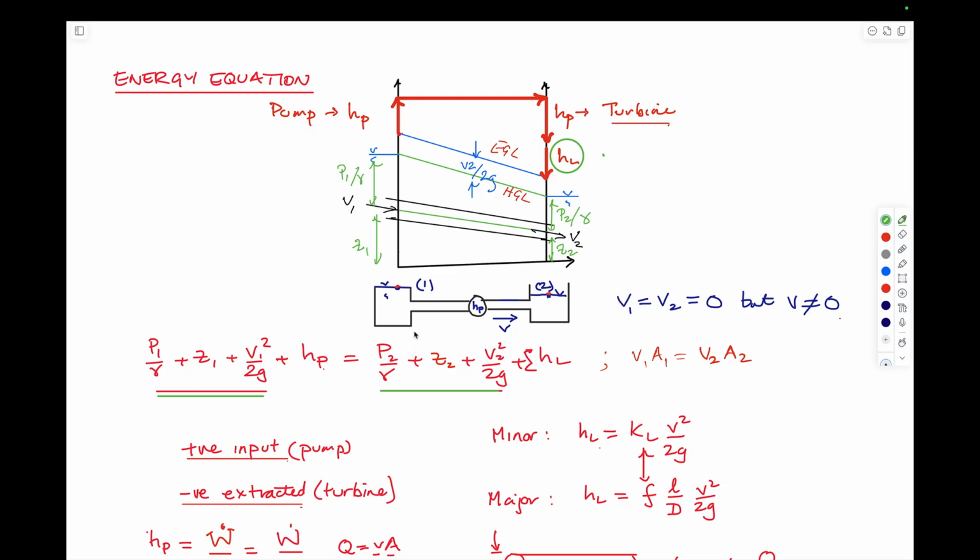Certainly we look in this case, I guess these velocities would be 0 if they're written on the top of the large reservoir, and if they're written inside the pump, they'd actually be finite, as they're shown here. But if you have an example where you have 2 reservoirs upstream and downstream that are large volumes, then you can remove those velocity terms by writing the equations on the surface where the pressures are 0 and the velocities are 0. And so you just remove the first 2 terms on each side, and you can concentrate on the remainders.